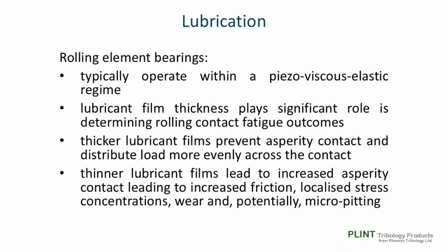This is the pressure viscosity effect, and it can cause the lubricant effective viscosity to approach that of glass. The fact that the lubricant is also effectively incompressible means that within the EHD contact, the film thickness is close to being constant.